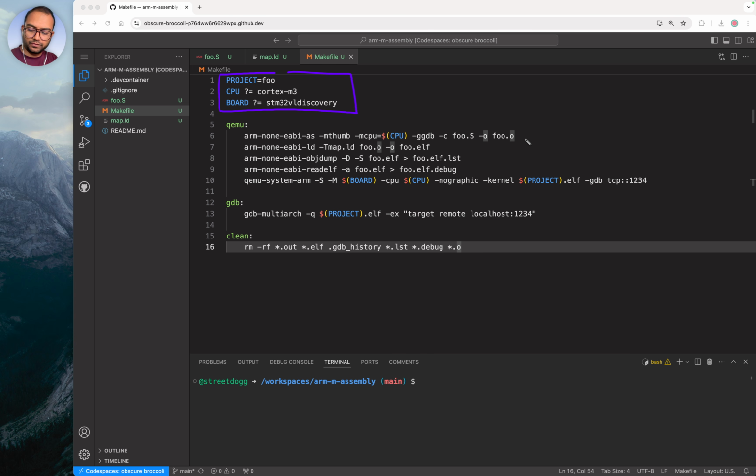So first off, let's come to these three lines later. Let me also change the color. Yeah, this one's good. Okay, we'll come to this in a bit. These two lines here, if you notice, we are taking the ARM assembler. AS is for assembler, and everything before that is a naming convention for the utility. But AS is the assembler. We say, hey assembler, take the foo.s file and please generate the foo.o file, right? So this is where we are going from foo.s to foo.o.